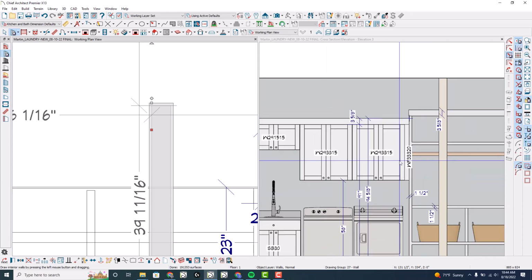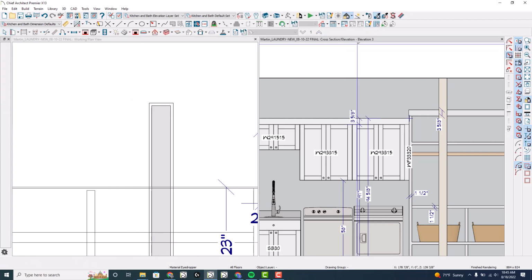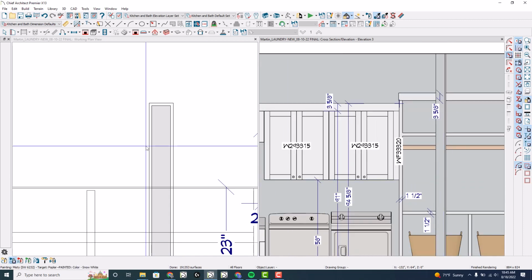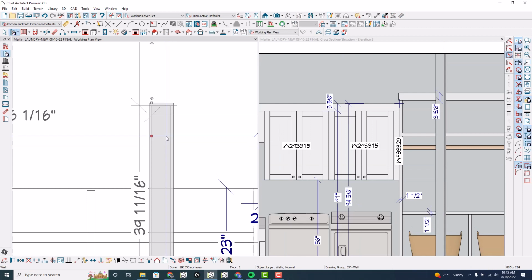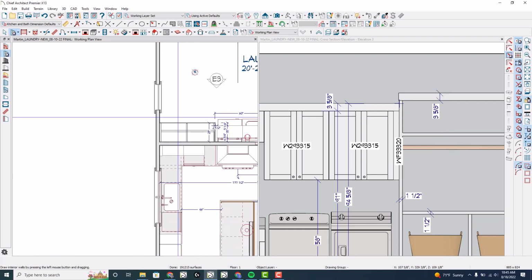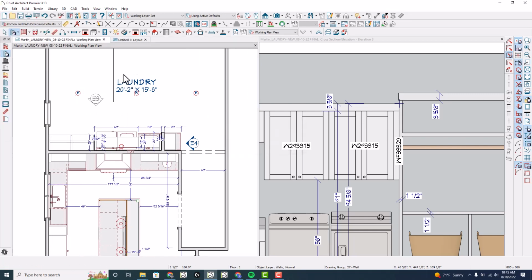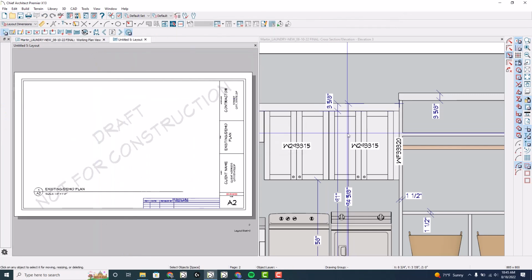And it works fine here now, interior 4-2, until, watch this, let's go into elevation. I eyedropper this gray material here, which is Sherwin-Williams Misty color. Make sure I'm in object mode, and I paint this wall that gray misty color. And now the 2 lines come back up. I'm a little bit baffled as to that. So we're going to come up with a different solution for this one. Let's delete that wall. The plan view looks okay. It's just this elevation doesn't.